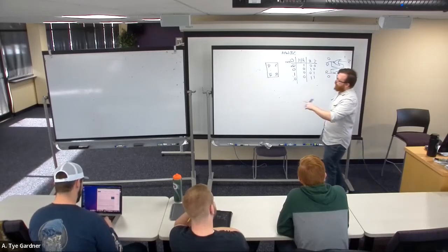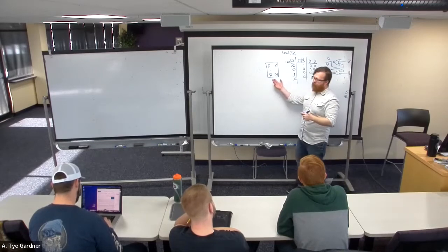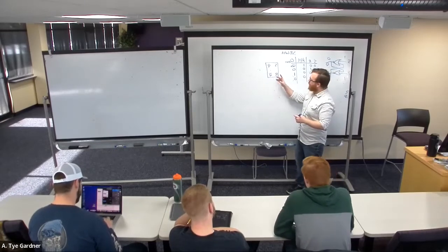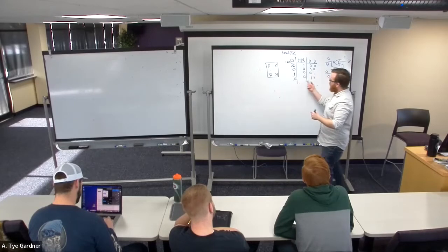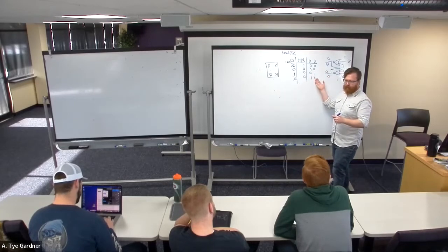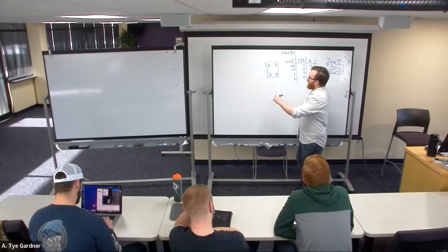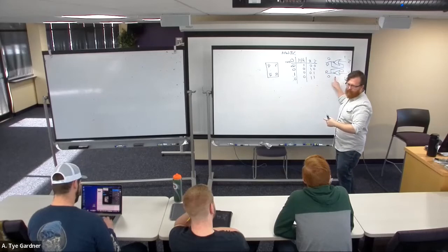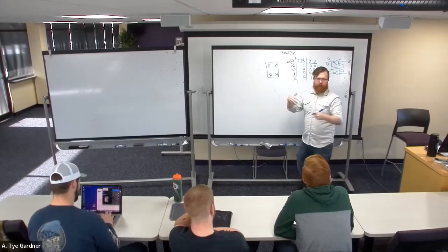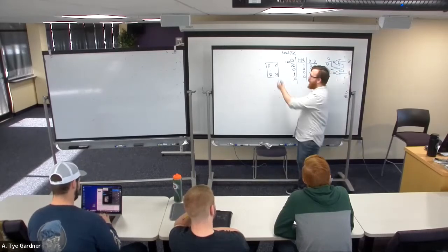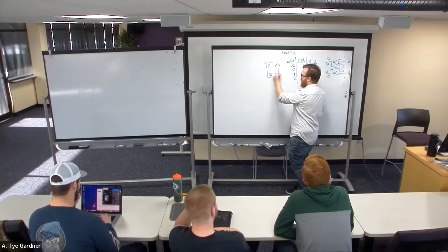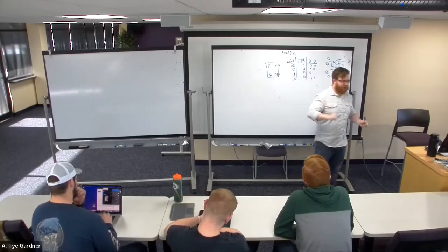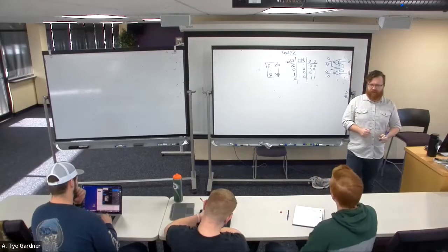So now, this one does have some issues because, well, the 1-1 is one issue, right? If we assert both of them at the same time. And we're going to want some other designs, but I want to point out that if I design this with NAND, we can have active low signals. If I want to indicate that they're active low, I can say, bubble, bubble, that is now an active low input SR latch.